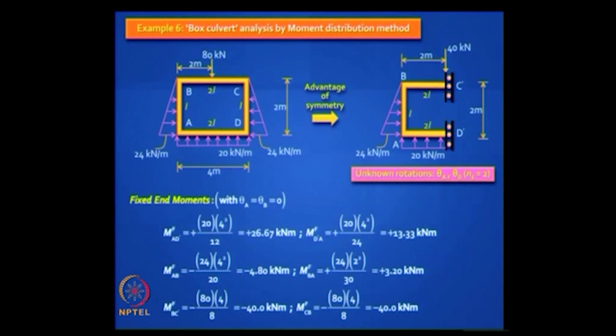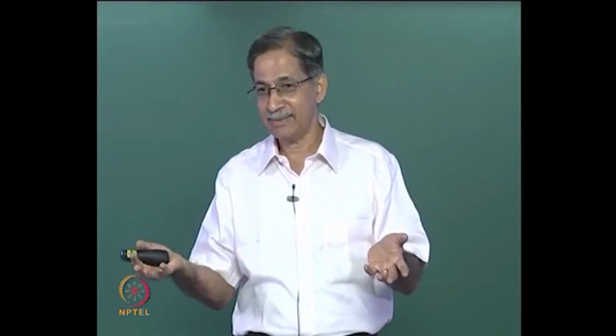So can you find out the fixed end moments? Yes, you know all the formulas. So let's say you know how to do all the fixed end moments. Of course you are more used to beams with loads acting downward. So when the loads are acting upward, you have to stand on your head in your mind and get the directions correct. Plus clockwise is always positive and anti-clockwise is always negative. So that's the only place where you can make a mistake.